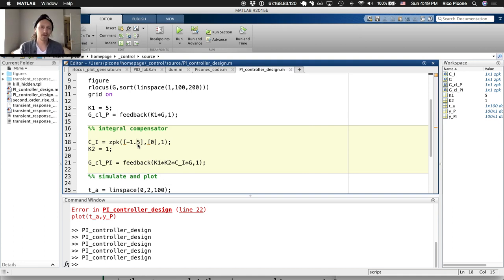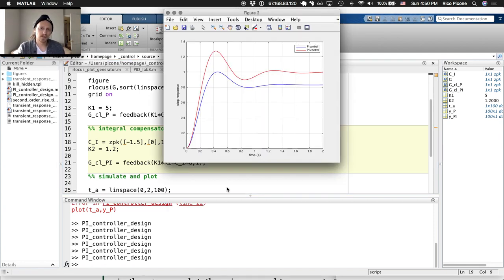We could look at the root locus and be a little bit more confident, but when you get to this point where you have this really rapid loop that you can close in terms of design, like you can tweak something and then check it, I like to play with it a little bit if possible, and if it gets difficult, then you can go back and look at the root locus and see if you can figure out what's going on. So let's increase our gain by like 20% and see how that affects it.